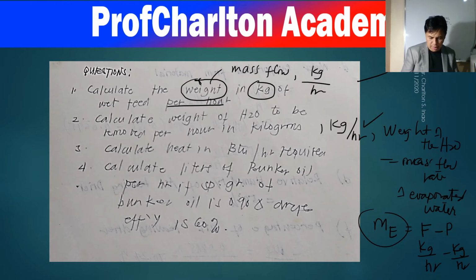Number two heat that I put here is the heat absorbed by the sand from 30 degrees to 115. So first, the heat that is required to evaporate the moisture, meaning from 7% to 0.5%. We have to have a heat to evaporate the moisture.